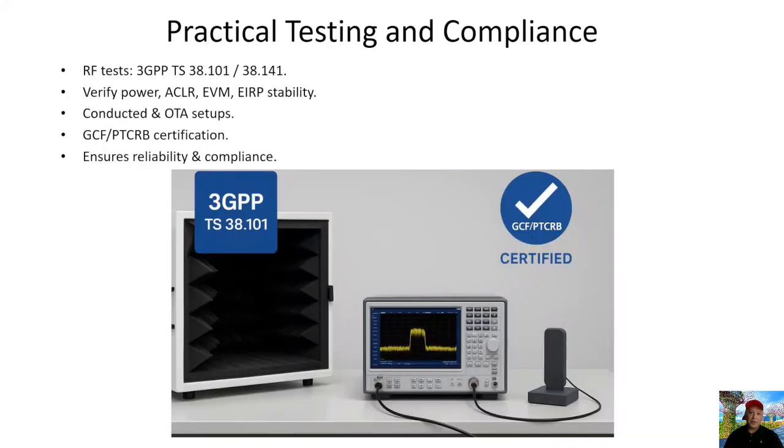Finally, every UE must pass 3GPP-defined RF conformance tests performed under controlled conditions. Standards such as TS 38.101 and TS 38.141 specify measurement setups, power limits, and performance metrics.